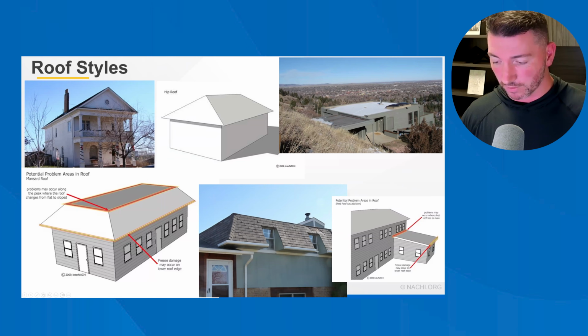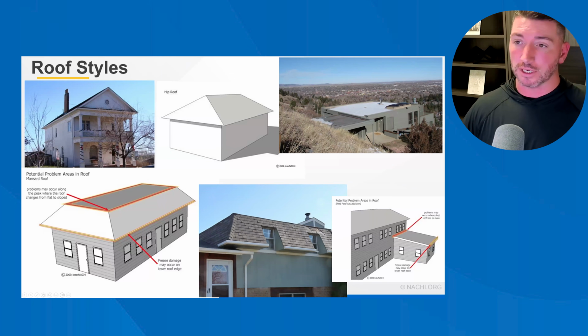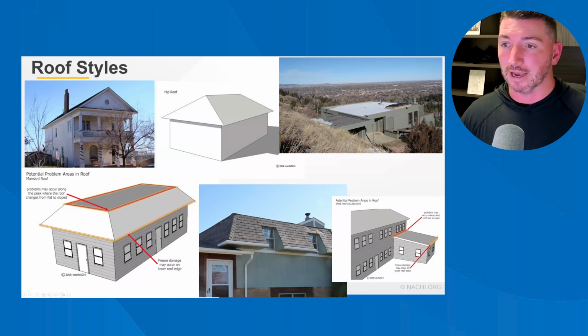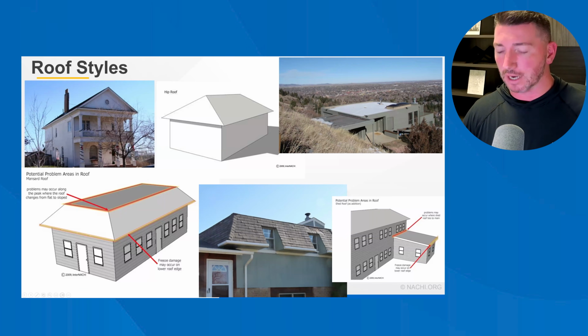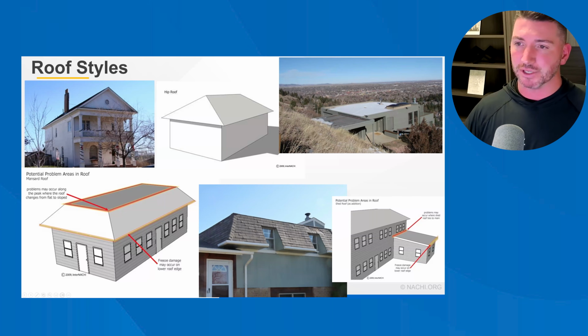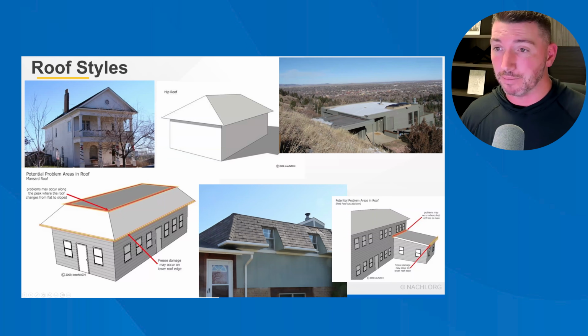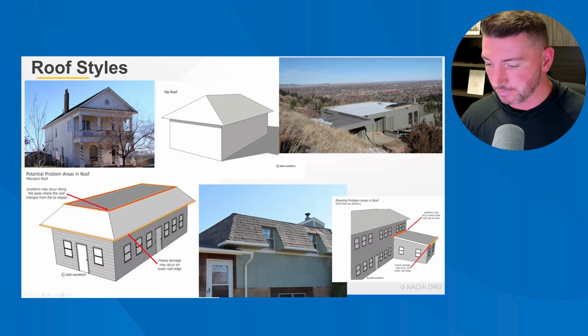Flat roofs are low slope roofs. Low slope and steep slope roofs have different requirements. And that is another terminology pet peeve I have, when it comes to people describing roofing materials as commercial versus residential roofing materials. That terminology is not correct. The correct terminology is low slope roofing material and steep slope roofing material, and steep slope is defined as anything over 2/12. It's not steep to walk on, but it's defined in the roofing industry as a steep roof application rather than a low slope application. And a low slope could be just about nearly flat, but that's how it's defined.